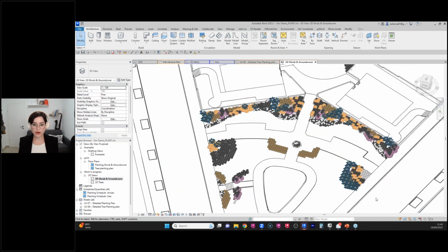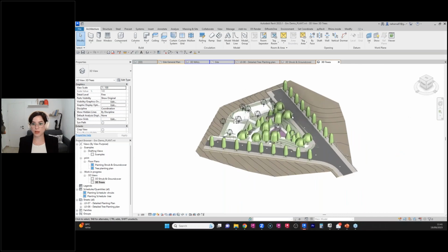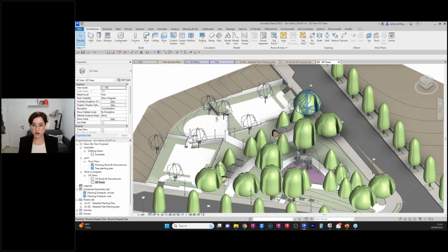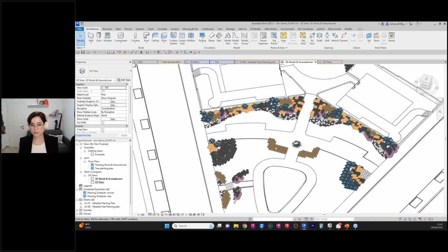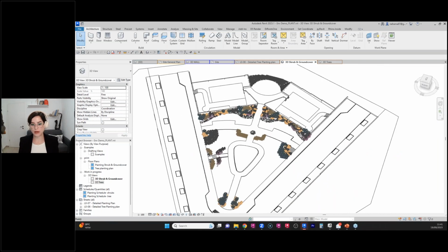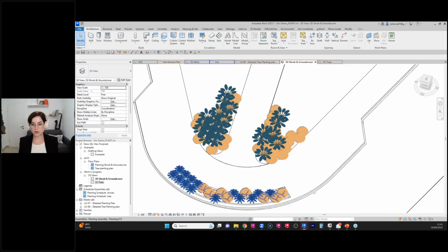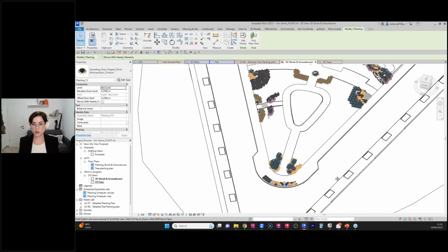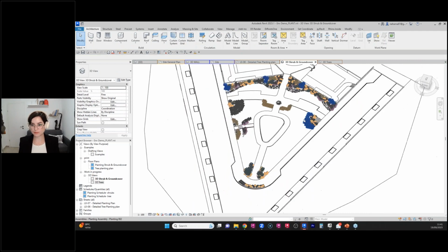We have a standard Revit landscape template, and within it you can find the basic geometries that you would need to create your planting libraries. There are different approaches to creating these geometries, as you can see over here. Each office and each landscape architect really prefers to see it in a different way, so we accommodate that. Revit is pretty great when it comes to managing information. All of the things that you see over here can then be scheduled and tagged very easily.